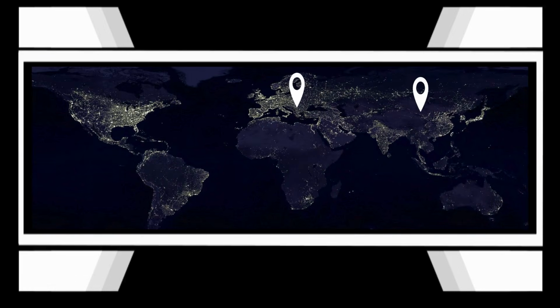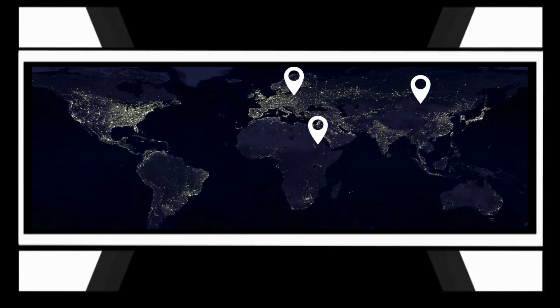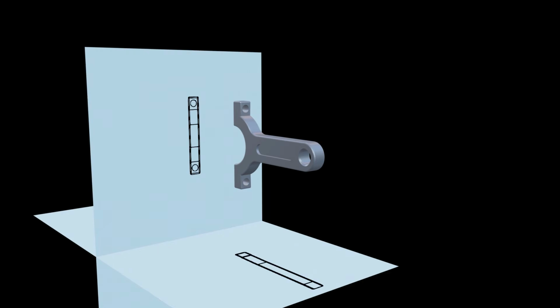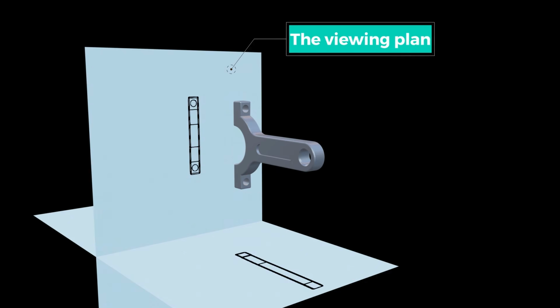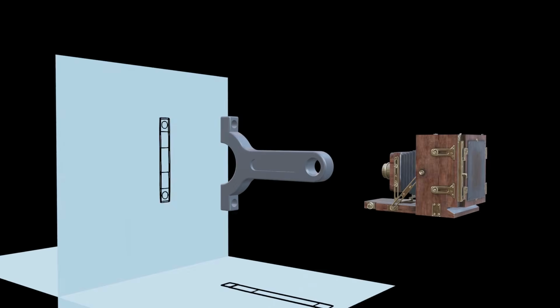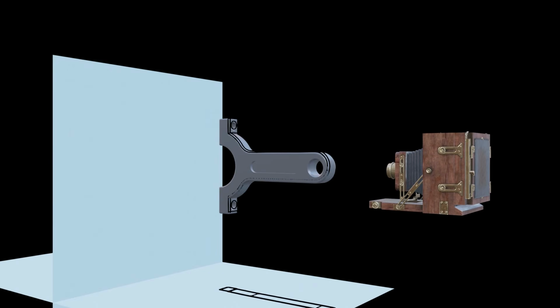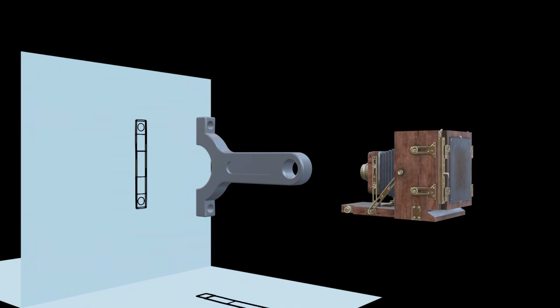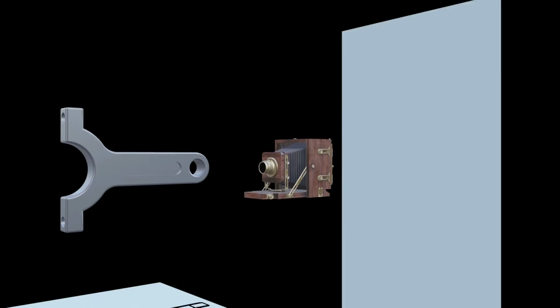First angle projection is commonly used in Europe, Asia, and other parts of the world. In this projection method, the object being represented is placed in the first quadrant of a coordinate system, with the object located between the viewing plane and the observer. Think of it this way. You are standing in front of the part, and you take a picture of it with a Polaroid camera that instantly prints the picture. In first angle projection, you would throw this picture behind the part. In third angle projection, you would put this picture behind you.